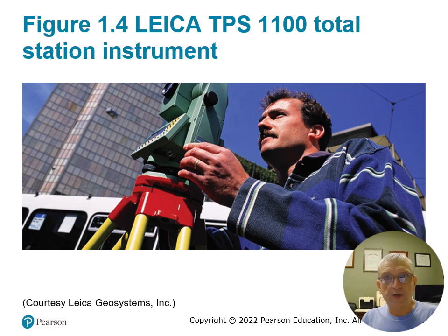But geodetic surveying is where we're taking into account curvature and refraction of the earth all the time, and that's because they're usually over very large areas, at least counties, maybe states, maybe entire regions, and we're dealing with precise measurements where those curvature and refraction corrections that may be within the level of tolerance for a boundary survey, they become very important for geodetic measurements.